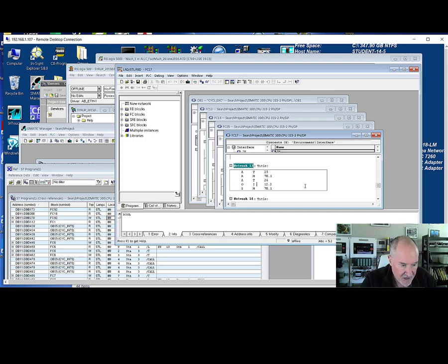So in this case here, we'll say I'm looking at my program and I notice that I12.2 is not on, and I go and figure out why I12.2 isn't on, and maybe it's a sensor that is bad or something like that. So that's a little bit of an example of how to do it in Step 7.